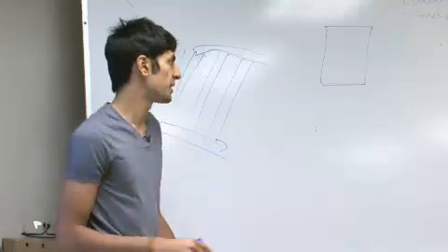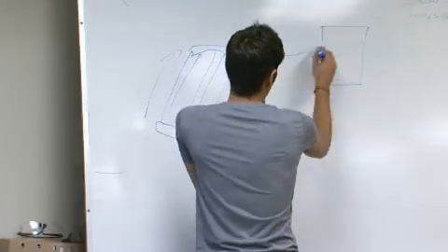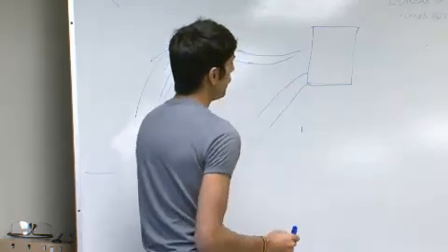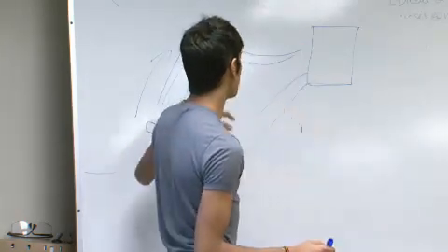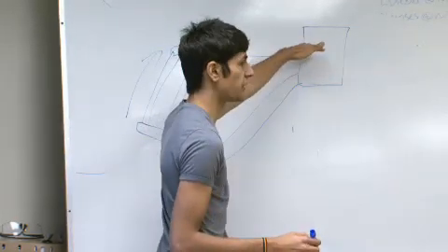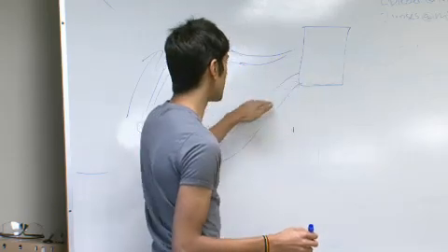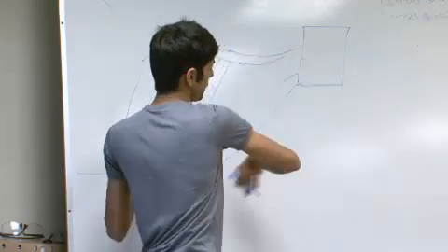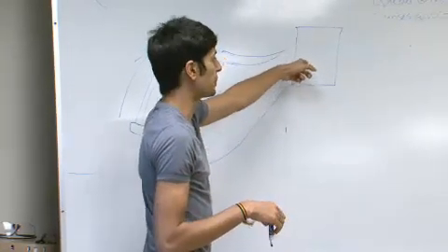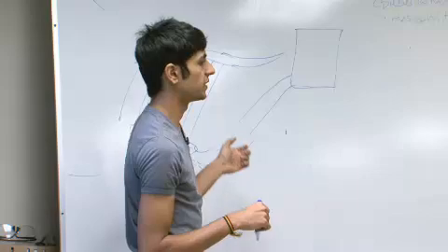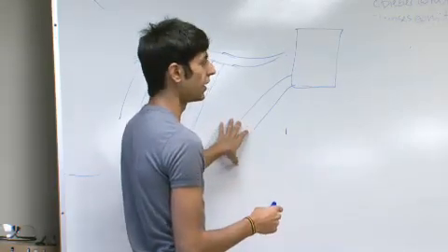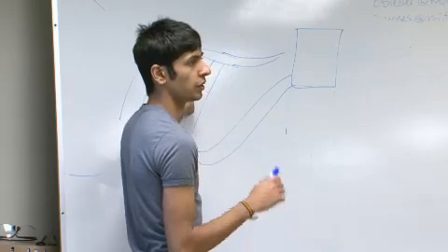If you connect this to a reservoir, you basically get a flow caused just by the temperature differential in the water. Hot water will flow into this reservoir, and it'll get displaced by cold water. So you're regulating the temperature and heating all of the water consistently, which is pretty cool because with a system based off of a thermosiphon, you don't need to throw in a pump or something like that to extract the water.